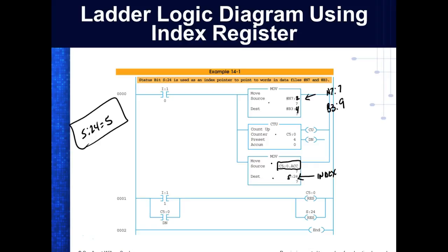Yeah, but what Larry's saying, it's going to be enabled all the time, and if I have this push button, it's going to be ripping through the scan time of the processor. So what Larry's saying is that we wouldn't even see the first time through the scan, and after that it would be right. But if I was doing the programming, I would do what? This guy here would be first. But it would happen in a heartbeat.